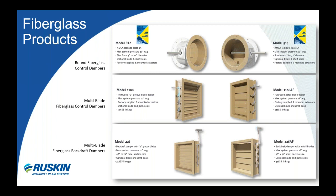Benefits of the use of fiberglass reinforced plastic include greater resistance to a wider range of caustics, solvents, and corrosives, making them suitable for odor control system applications, competitive costing compared to 316 stainless steel material of construction, and lighter weights compared to the steel alternative, making it easier for the installer. Fabrication features of Ruskin's line of FRP products include UV protection for outdoor installation. They include a low flame spread rating, intumescent coating for low smoke, use of high quality vinyl ester resin, and we also provide these dampers with flanges customized to match adjoining duct flanging.